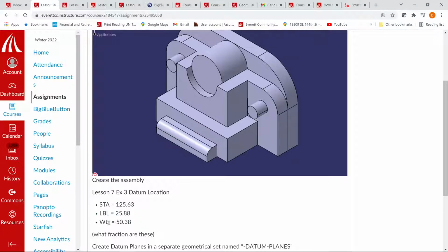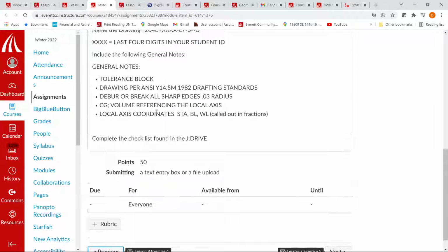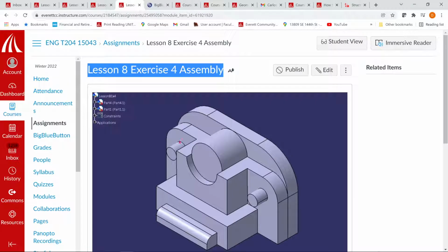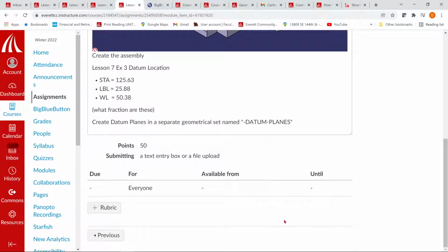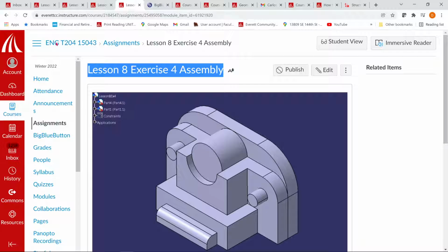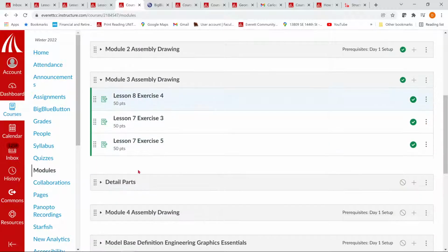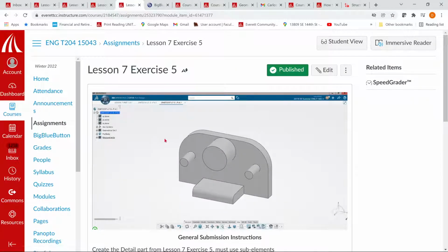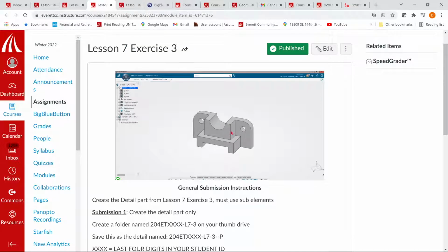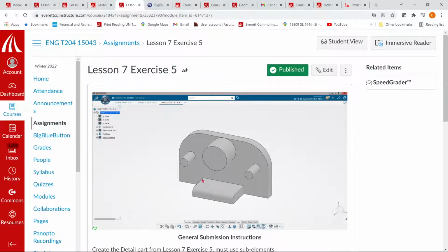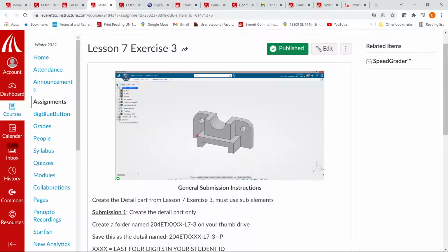So I've got to create a local axis system on this part here. Now, this piece here is in front. Oh shoot, what happened? Is front of here. So these two pieces, they mount together. The back side touches the front face here. So this corner right here will be my local axis for both parts. When I create this part, we'll go in the negative x direction, and for this part here, everything will be in the positive x direction.